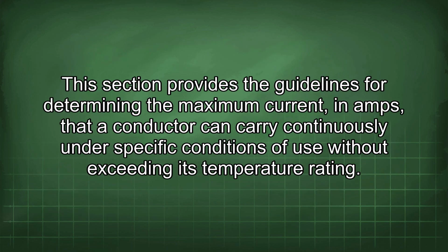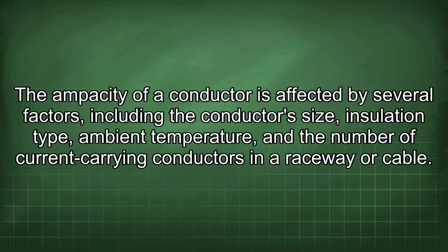This section provides the guidelines for determining the maximum current in amps that a conductor can carry continuously under specific conditions of use without exceeding its temperature rating. The ampacity of a conductor is affected by several factors, including the conductor's size, insulation type, ambient temperature, and the number of current-carrying conductors in a raceway or cable.